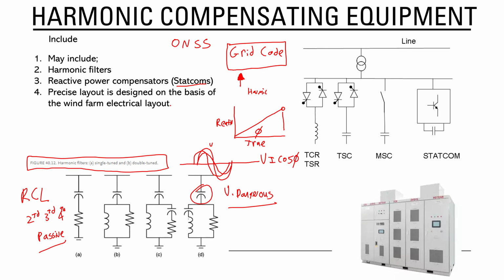And reactive power is not good for a load of reasons, but the main two reasons are, one, because reactive power increases theta, cos theta is dropping, therefore the amount of real power we can get out of the system is lower than it would otherwise be. Secondly, the current for a given amount of real power needs to be higher than it would otherwise be, and that current is flowing through the same conductors, so the losses due to that current flow are higher than they would otherwise be. So reactive power, not good, don't like it.